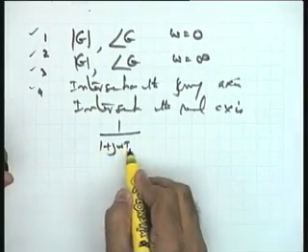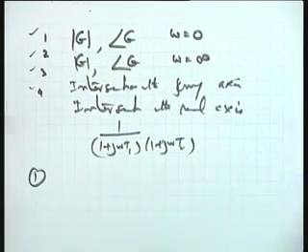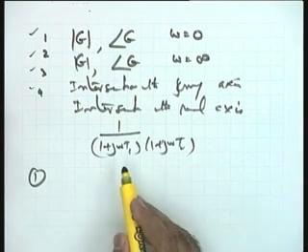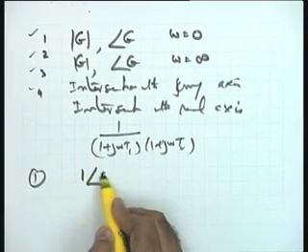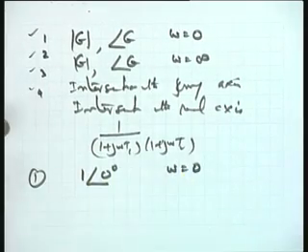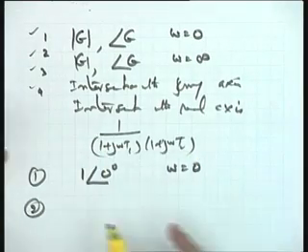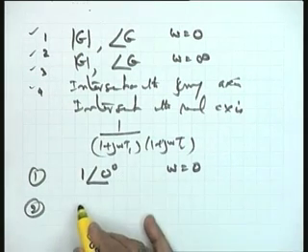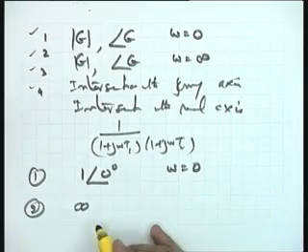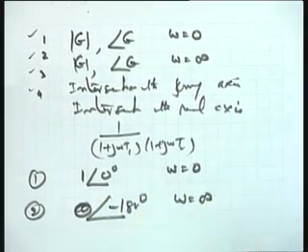1 plus j omega t1, 1 plus j omega t2. Help me with the first point please. What is the magnitude and angle when omega is equal to 0? You find in this particular case the magnitude is 1 and angle is 0. So you have 1 point at omega equal to 0. Number 2, what is the magnitude and angle when omega is equal to infinity? Corresponding to omega equal to infinity, I am writing straight away 0 angle minus 180 degrees at omega equal to infinity.